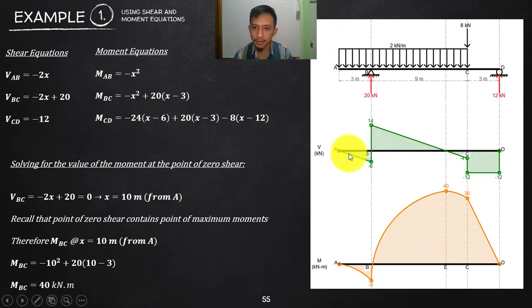So that is a negative line, straight line. And again, this is first degree, isn't it? Going back, the derivative of moment is shear. The derivative of shear is loading. What does that mean? If we are differentiating, we are trying to reduce the degree of the equation.